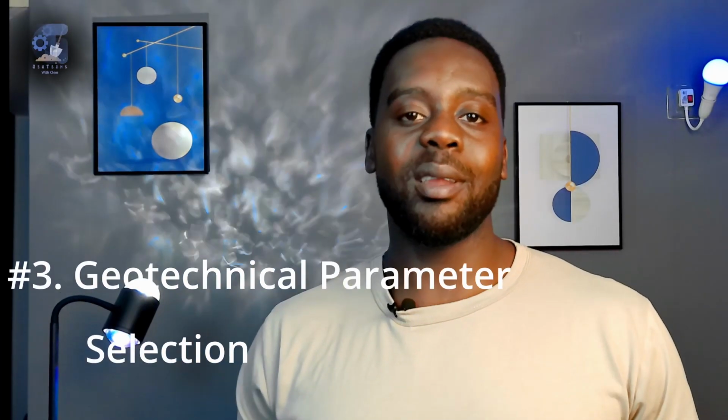Finally, when selecting parameters to be used for the foundation design, a couple of factors are taken into account: the extent, quality, and adequacy of the ground investigations, reliability of the geological and geotechnical analysis models, the appropriateness of the test methods, the representativeness of the soil parameters for the likely field conditions, the method of analysis adopted for the design, and the likely effects of foundation construction on material properties.